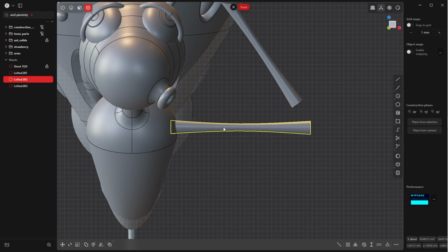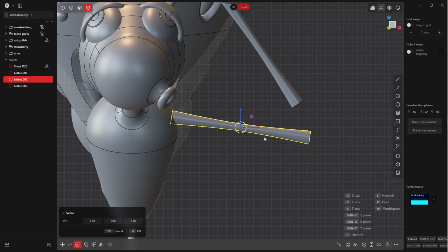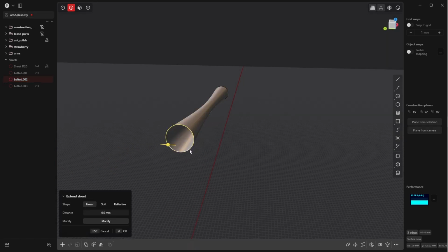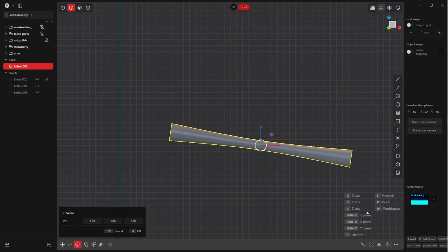If you want to scale this guy without having any distortions, because let me exaggerate, when I have a situation like this, and if I scale right away along the x-axis, we get distortions like this. Shift H for isolating this, Shift J for closing this end, and also the other end, Shift J. Go again to the front view, press S, and change the pivot point. Enable snapping in this case. And if we catch the middle, now we can scale our object without skewing it.